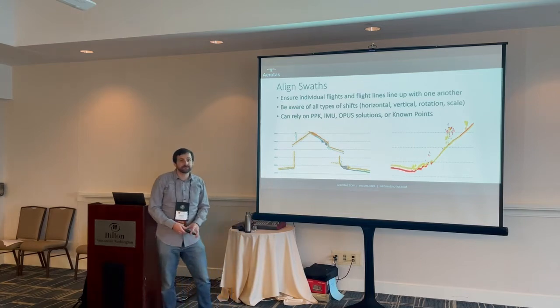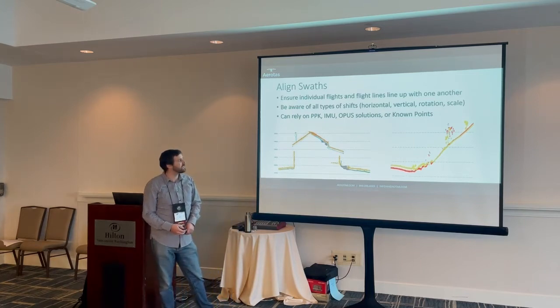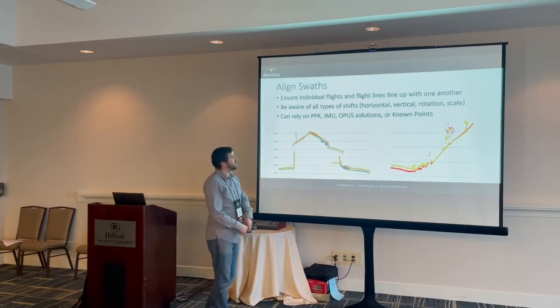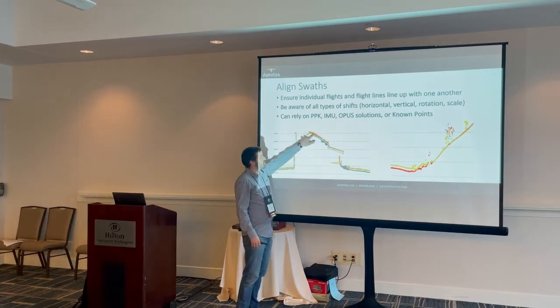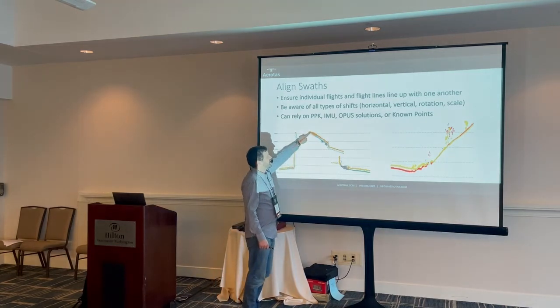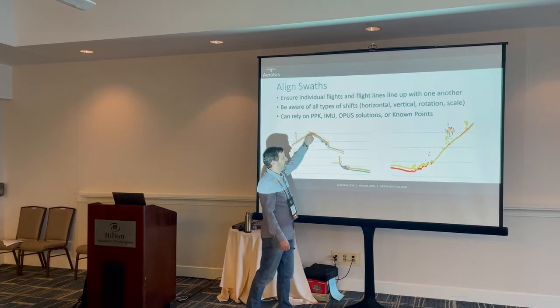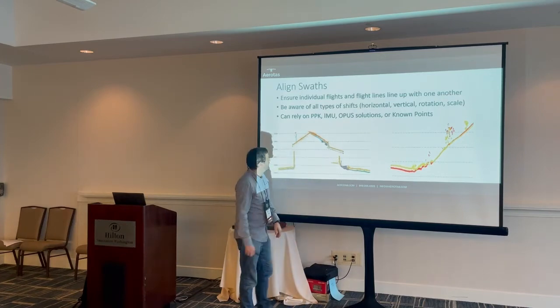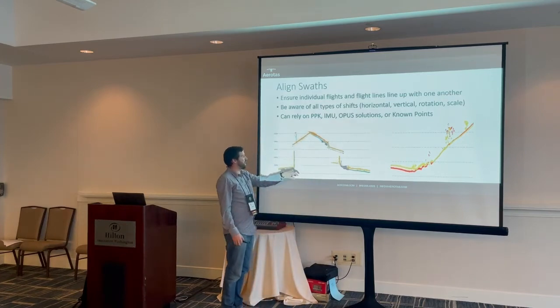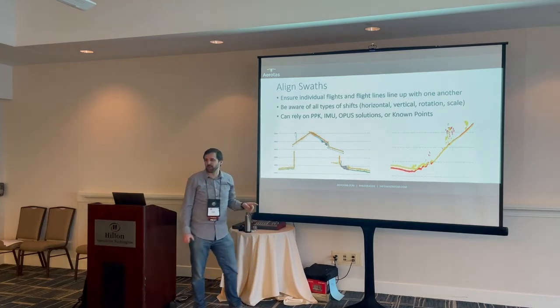And sorry, one more follow-up question. Sure. Processing this, is it a similar workflow to just manually combining two terrestrial scan stations, where you pick tie points? Yep, pretty similar. There are a lot of different statistical ways to do it. Sometimes you pick tie points. I really like using houses. This is a great example because you can actually see a lot of these points that need to be aligned pretty precisely. This right here is actually an example of a photogrammetry point cloud and a LiDAR point cloud.